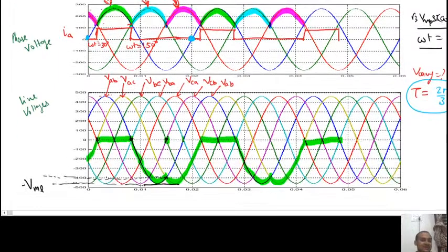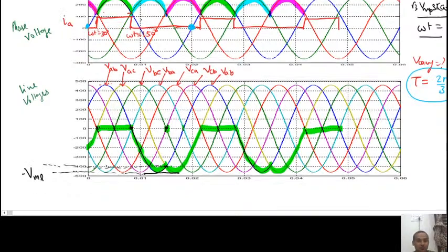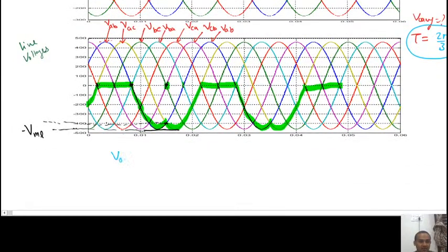Now, especially in 3 phase, you have to take care of limits very carefully, because if you change the limits here, your curve will also change. So if I take this blue one, VBN, then you must take the nature of VBN also. Let me show you: I am calculating V naught average, taking VBN with omega t.